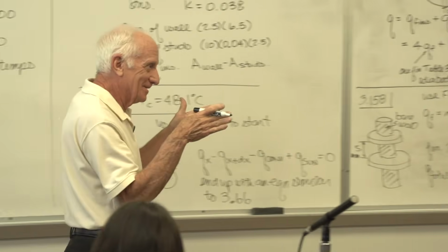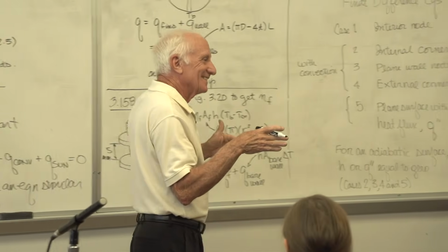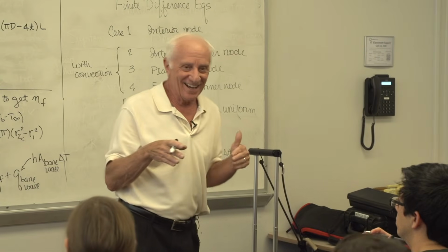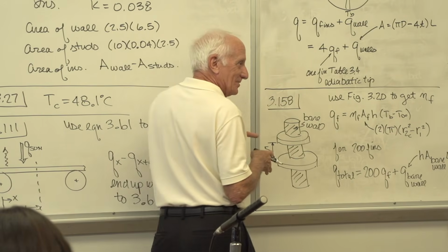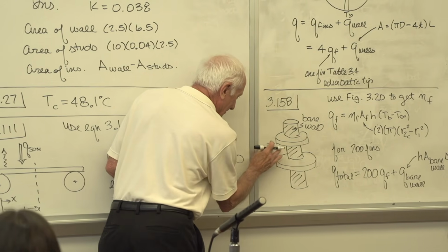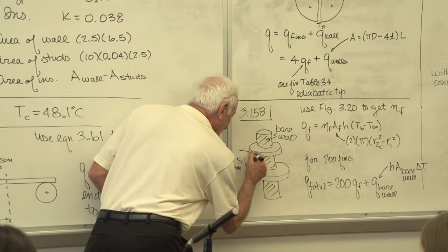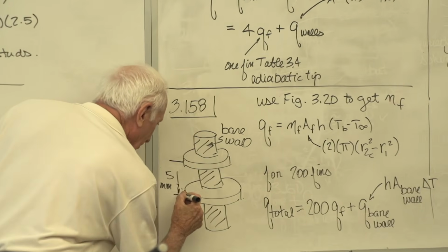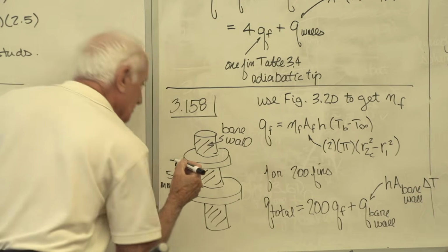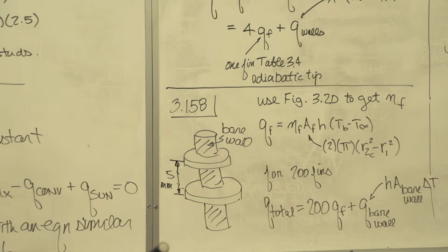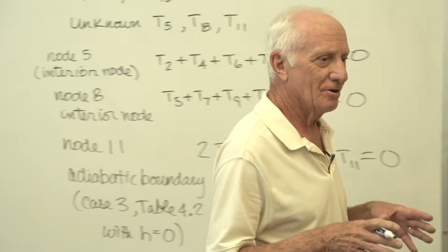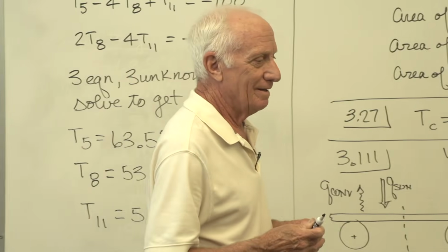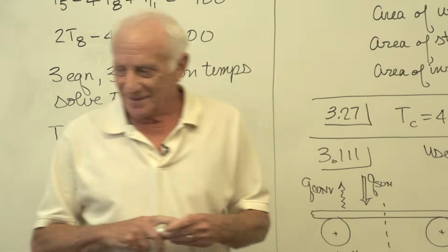No. What's the correct way to say that? Center to center, right? So what does this mean? 5 millimeters, center to center. No, you got it wrong. Your area's wrong. It's from the middle to the middle. People make mistakes like that, which seems small, but when you multiply it by 199 spaces, it becomes rather large. So get the areas correct on problems like that.